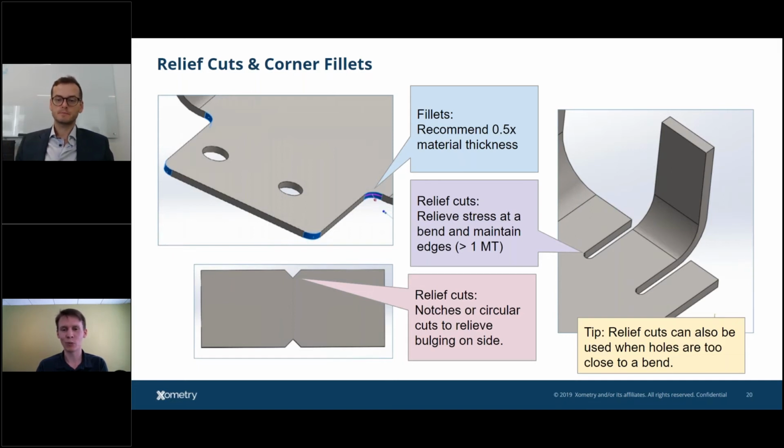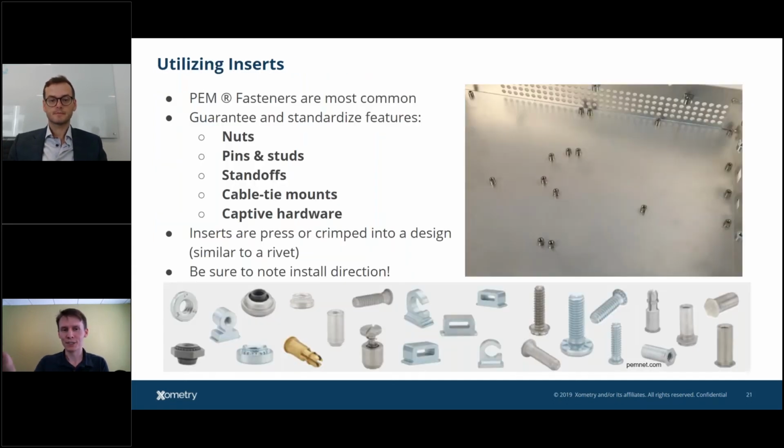And yeah, installing hardware, if your hole all of a sudden becomes an oval or has a big flare out lip, again, you're going to have a bad day. So yeah, talking about PEM hardware. This is not an advertisement for PEM fasteners, but they just kind of own the market with sheet metal parts. You can tap sheet metal. I'll say that, and I'll admit to that.